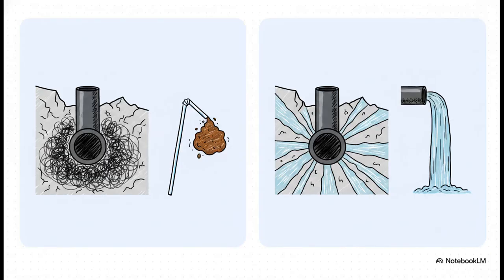Let's actually contrast these two realities. If a well has a positive skin effect, say an S value of positive 10, it is heavily damaged. The math shows the reservoir treats this well as if its radius has shrunk down to a fraction of a millimeter. It's literally trying to drink a thick milkshake through a microscopic cocktail straw.